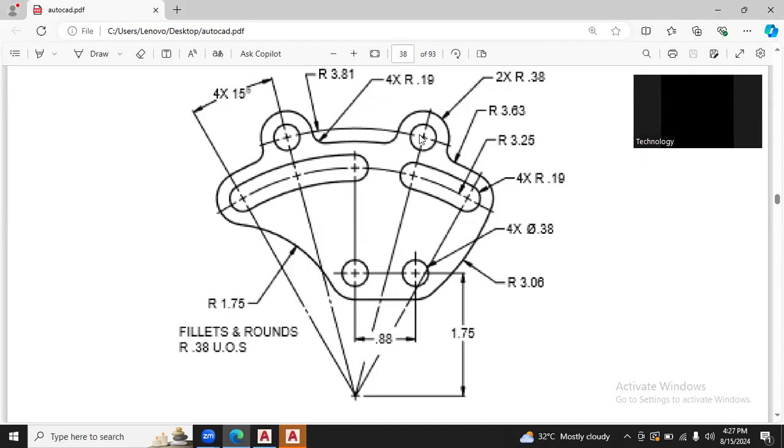All right. But before jumping towards these circles, you need another reference line for your height. The reference line given is by the radius 3.81 actually. And the reference for this radius is the exact center point, which we have already chosen as 0, comma 0.